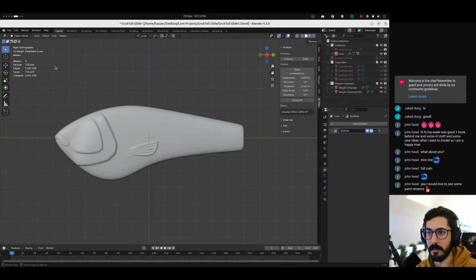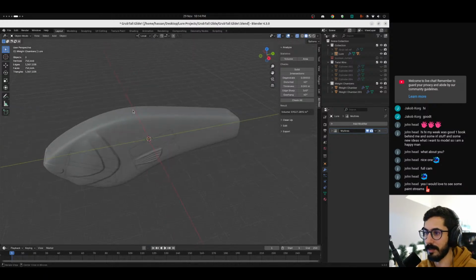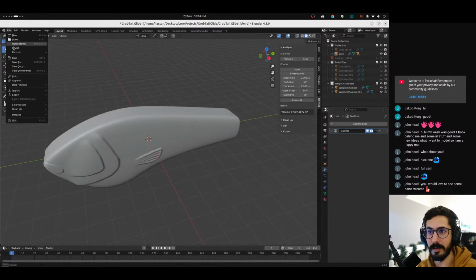What the hell happened here? I just learned a Blender shortcut by mistake. So Alt-Z usually enables transparency, but if you do Alt-Shift-Z or Z, it turns the grid on and off, and even these. It's fun when you learn stuff by mistake.